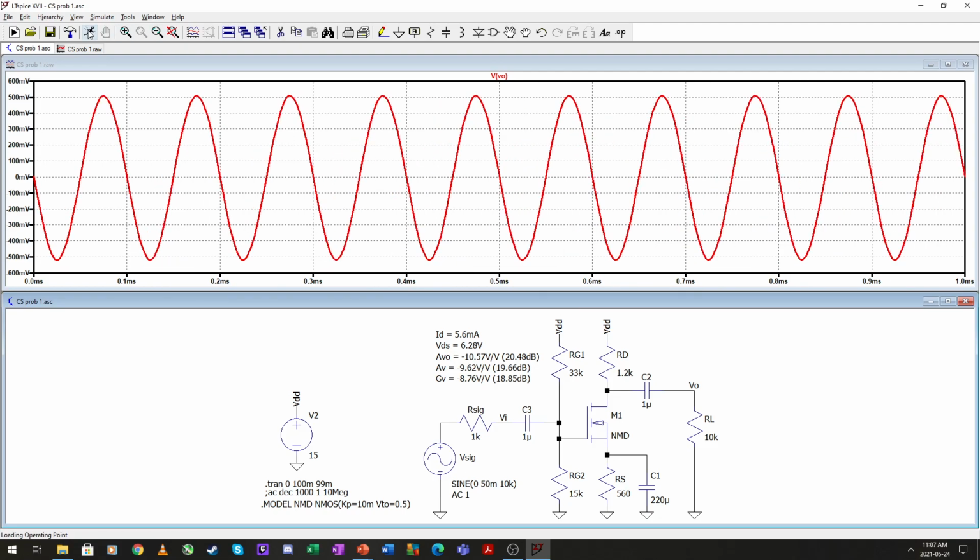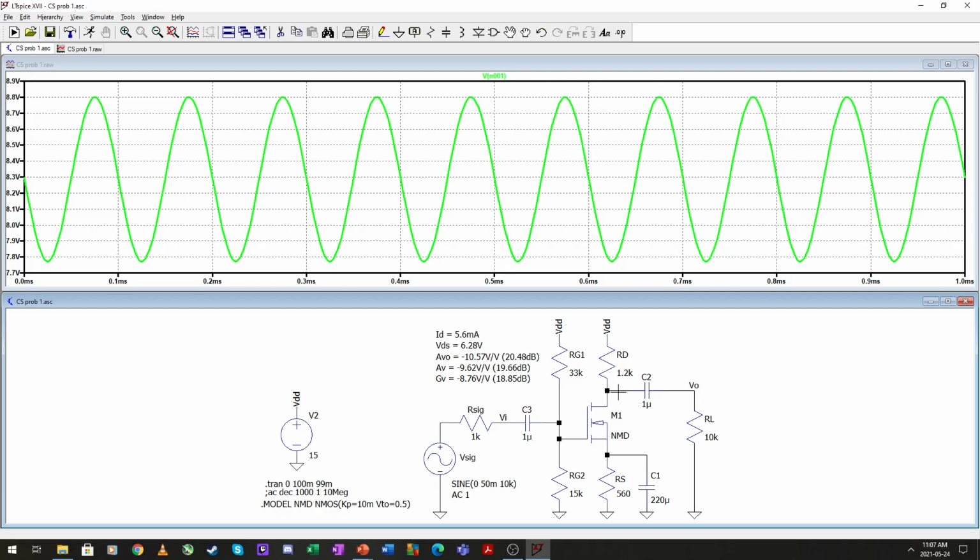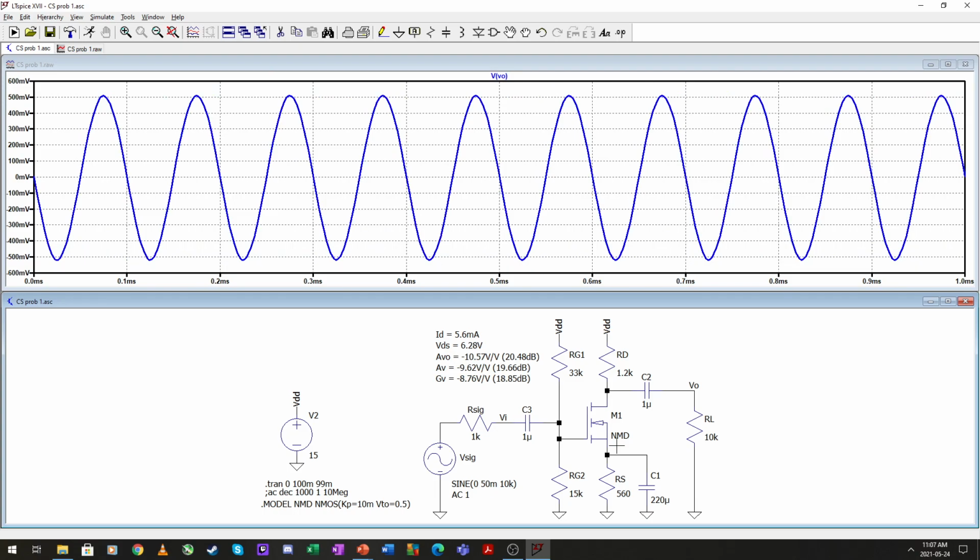Okay, and if you wanted to design for an exact gain of 10 with the Kn value that we had, just increasing this a little bit actually fixed the gain kind of nicely. But if you increase this too much, the drain source voltage will drop and you can't achieve a very large output swing. So just be careful of that. But yes, make this 1K again.